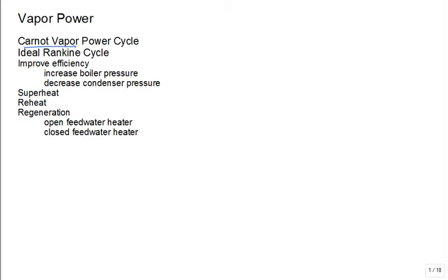And then we move away and we say, let's try and make it a practical Carnot, as close to the Carnot as possible, with a real pump that wants water into it, like saturated liquid coming into it. Well, then we move into the ideal Rankine cycle. We can still have maximally efficient turbine, maximally efficient pump, all the devices being internally reversible, no friction, no pressure drops, things like that, but we still see that our thermal efficiency has fallen.